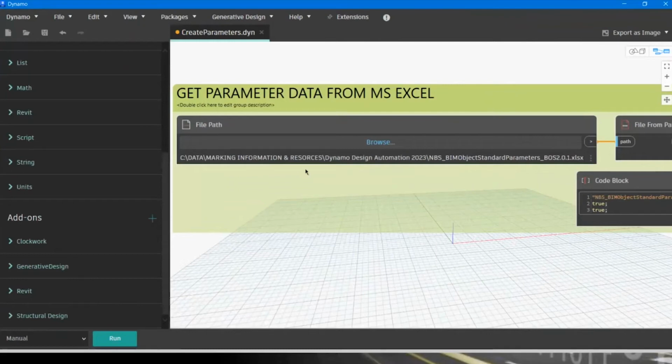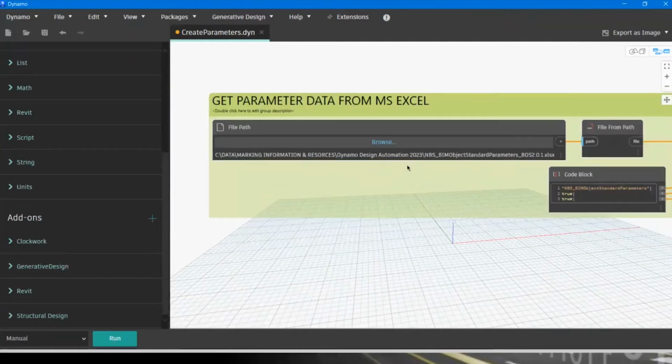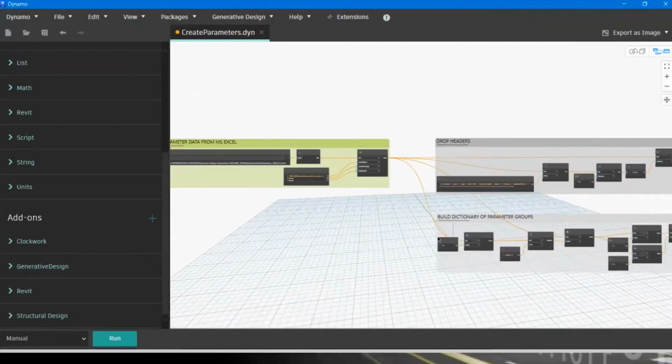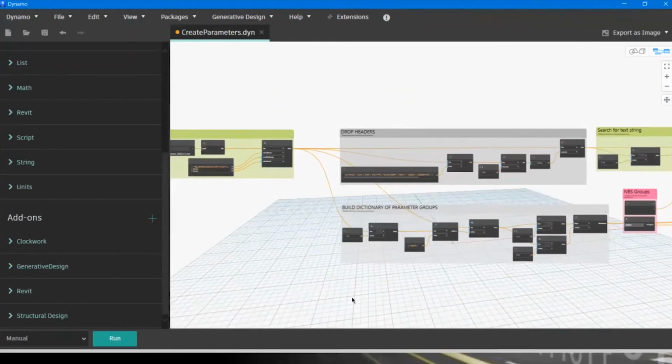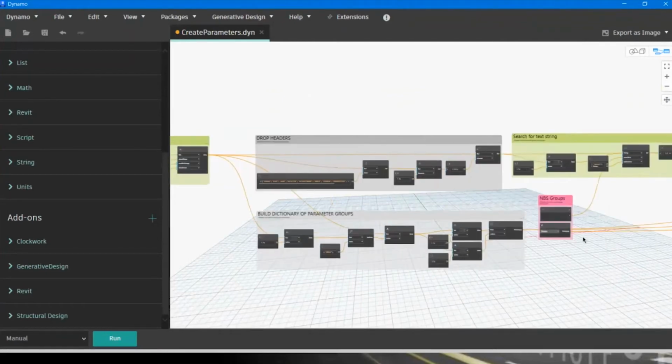Well, basically, what this is going to do is allow us to put information into our Revit model based on the MBS requirements. Now, the MBS requirements will obviously be generating parameters for Uniclass 2015, but also for an IFC delivery and also a COBie delivery. Now, there's literally hundreds of thousands of parameters that can be used in this particular workflow. And normally you would actually have to generate all of these manually.